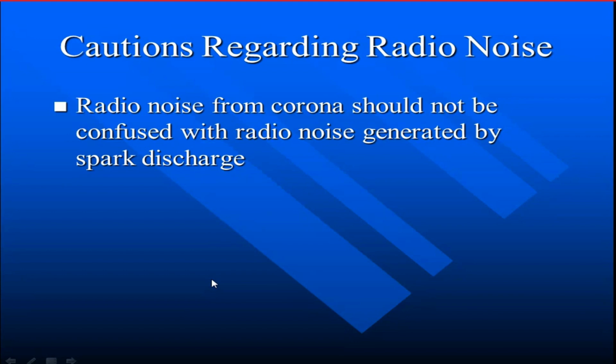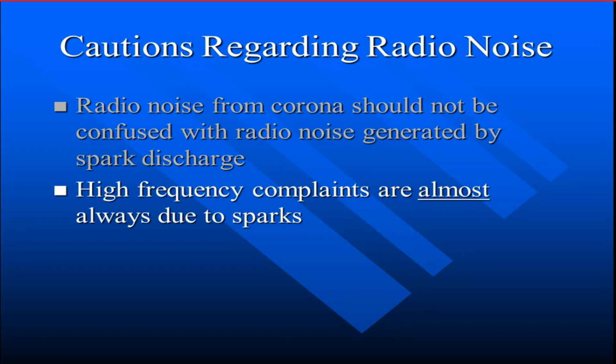Okay, so what exactly is radio noise and what are the cautions regarding radio noise? Let us see. The radio noise from corona should not be confused with radio noise generated by spark discharge. Spark discharge noise and corona noise are two different things. High frequency complaints are almost always due to spark.